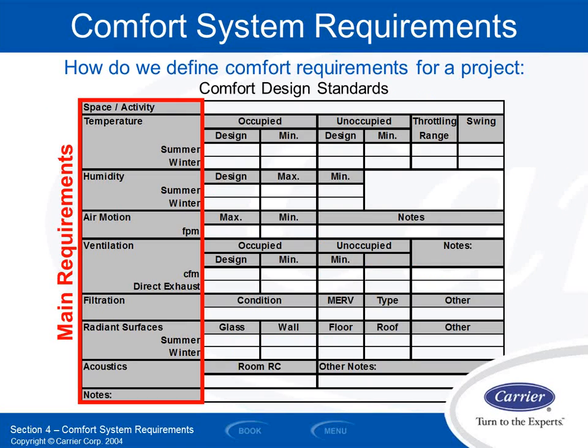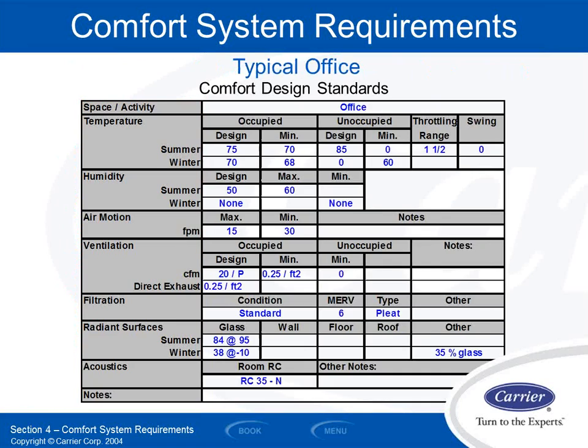So sometimes we use these charts when designing or setting up a system. It's easy to fill out in advance, so I know what I'm targeting, and then my building owner or occupants or whoever can agree upon the things we're trying to set. So, for example, I mentioned heating and cooling set points. Typically, my design is 70 for heating, 75 for cooling. I know that in some people's designs, they've been dropping that 75 number cooler and cooler, and people want my building to get down to, you've got to make me 69-degree air.